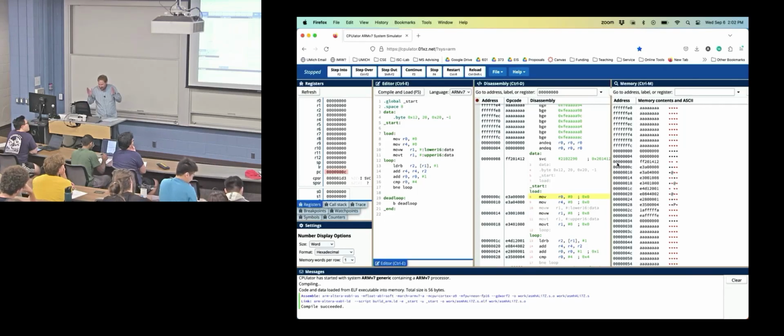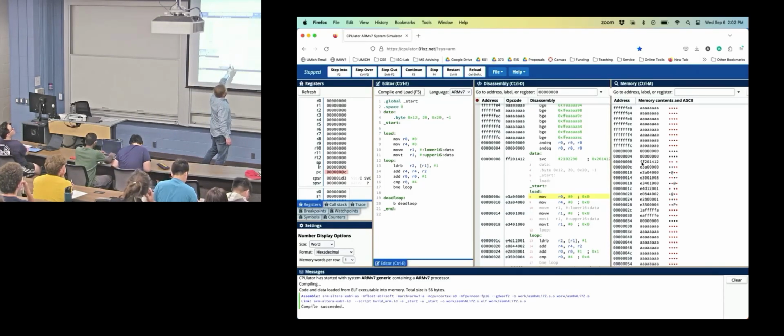And then we said byte. Byte was a command that was instantiated. In this particular case, we got 12, 14, 20, FF. So here the assembler figured out, you put -1, it turned that into 2's complement. This is all in hex. So 12, I think 20 is 12, right? Or no, 20 is 14 in hex. Okay, so there's the memory locations. So it's been put into memory.